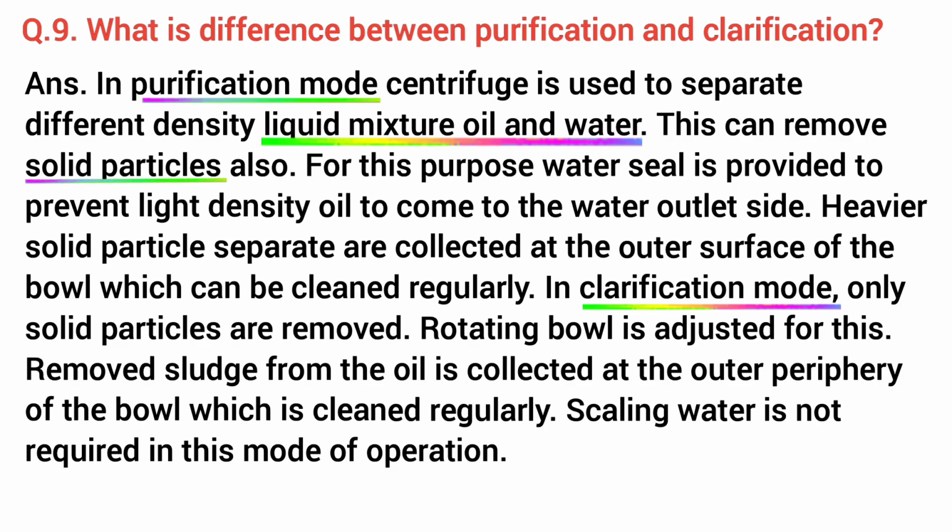In clarification mode, only solid particles are removed. Rotating bowl is adjusted for this. Removed sludge from the oil is collected at the outer periphery of the bowl, which is cleaned regularly. Sealing water is not required in this mode of operation.